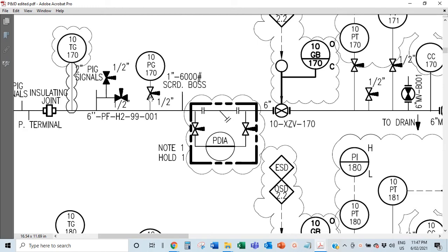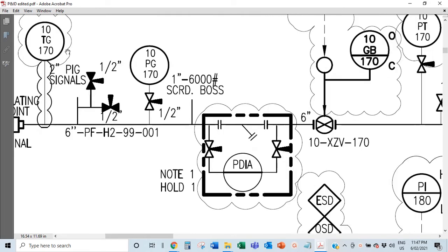So you have this here. Then you have this, which is also another needle valve. Most times when you lock them closed like this, it's because you want to put future instrumentation like gauges or transmitters on them. So here, this is a pressure gauge. It's different from the temperature gauge. This is just to look at the pressure also. So you come here, you can see what is happening here with the gauge locally.